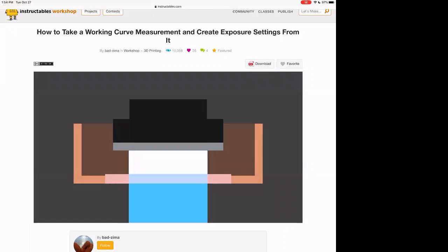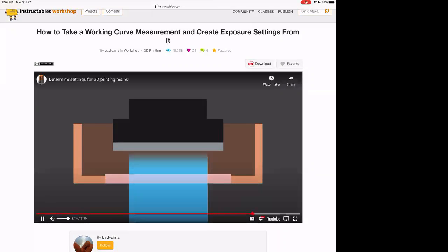Ideally, a 3D printed layer would solidify all at once when exposed to light. However, in practice, it is more complicated. We wish the light intensity was perfectly uniform throughout the thickness of the layer. In reality, the light intensity drops off as we move up through the resin. This is true for even thin layers. So even 100 micron layers, even 50 micron layers, because these resins absorb so strongly, there is a gradient in polymerization as you go from the window into the resin.